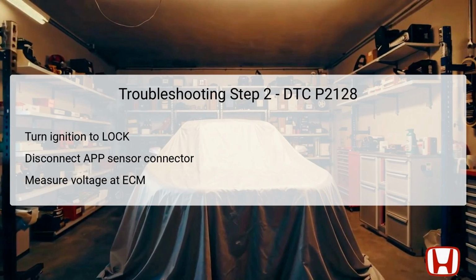Test point 1 refers to terminal number 2, LT blue wire on the APP sensor 6P connector, while test point 2 is terminal number 3, gray wire, of the same connector. The voltage reading should be around 5.0 volts. If you achieve this voltage, the APP sensor is likely the culprit, and replacement is warranted, followed by repair verification. If the voltage does not reach that level, the issue lies with the SG5 line, requiring further investigation.